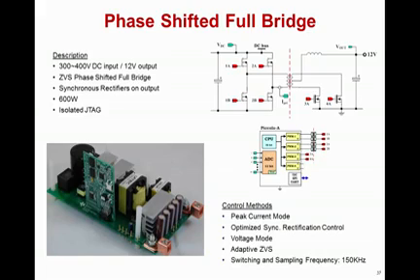This is our phase-shifted full bridge kit, the block diagram of which is in the right-hand corner, and again you can see the synchronous rectification FETs on the right-hand side of the diagram and the full bridge on the left-hand side. The dotted red line indicates isolation between the two because typically there is a high voltage bus and a low voltage DC bus inherent in this system.